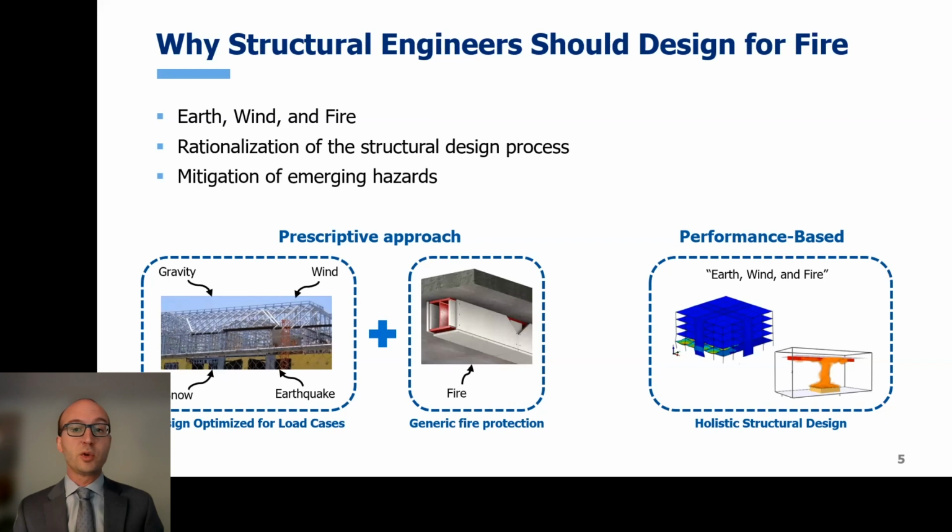So alongside the prescriptive approach, structural engineers can be engaged to design for fire. Structural engineers already calculate and optimize structures against various types of loads, and fire is another type of structural load. Structures should resist the heating from fires as they resist the acceleration forces from earthquakes and the pressures from wind.